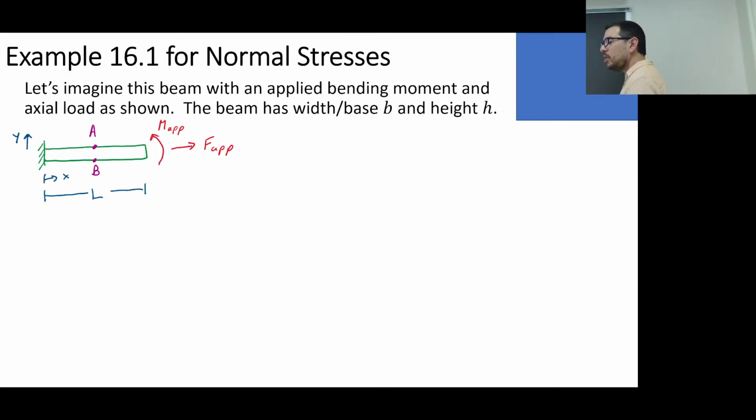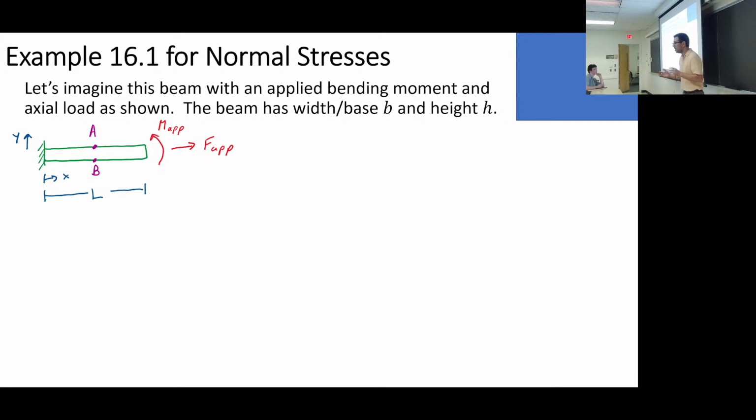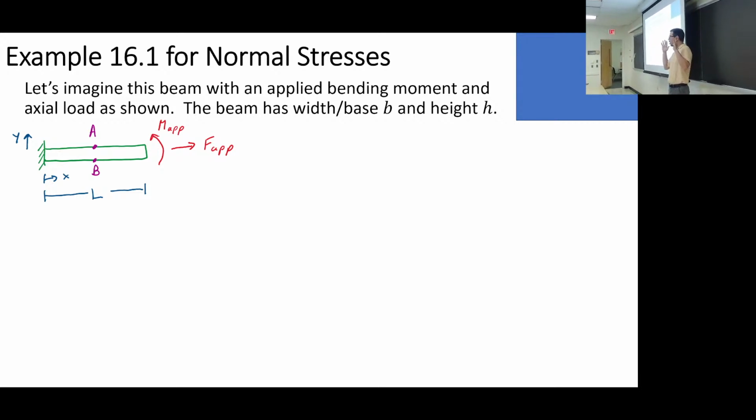I guess I could say thermal. That's kind of in the bar category. If I heat a bar up and it's got no wall on the other end, like I've got a bar that's free on one end and I heat it up by 100 degrees Kelvin, there's zero stress. I've got strain, but I've got no stress. When I constrain it, I can then have a compressive stress. So I could have added thermal here, as long as it's constrained thermal.